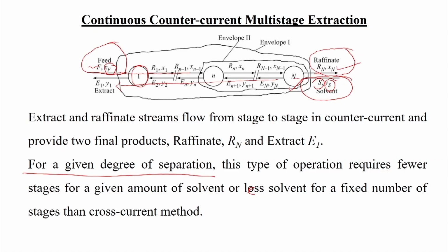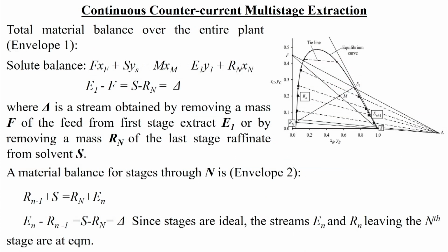Okay. Here we will also discuss the step by step procedure for the design of the multi-stage countercurrent extraction process. Before that, we need to understand the process. So, we have this binary zone, this is the raffinate arm, suppose the plait point is somewhere here, and then this is the extract arm, on a right angle triangular diagram.